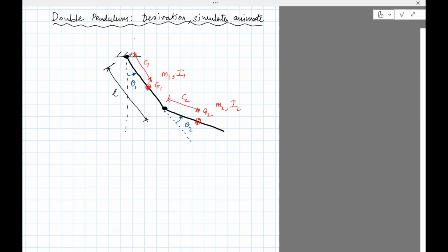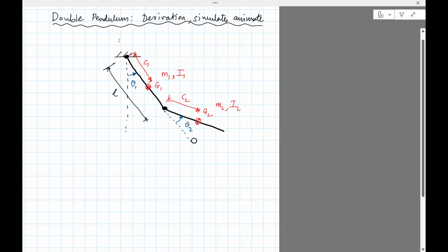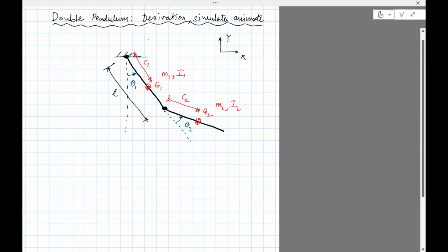Okay. Now that we have that, that would be your problem description. You need to derive the equations with those things given to you. So the way we'll do this is we'll assign coordinate frames. By default, the horizontal is X, the vertical is Y. So we'll start at assigning frames. So let's do with this. X0, Y0, that particular frame is fixed. It doesn't change. It's the fixed frame. The origin associated with that is O.